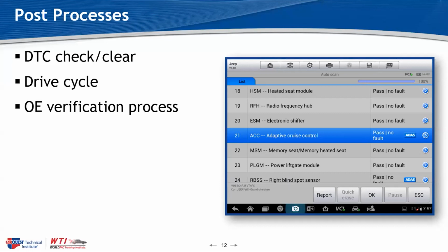We always have to remember, I did it wrong on purpose. That's exactly it. We always have to remember that just because the scan tool says it calibrated successfully, that really doesn't mean anything until you verify it. Right, and you can do that and get no DTCs by just doing a code scan and check, and it may not code ever, or it may not code for a long time, or it may code on the first drive. I'd really not want to do the research to find out when. It's much easier for me just to do it the best I can, as close as I can the very first time, and go on from there.